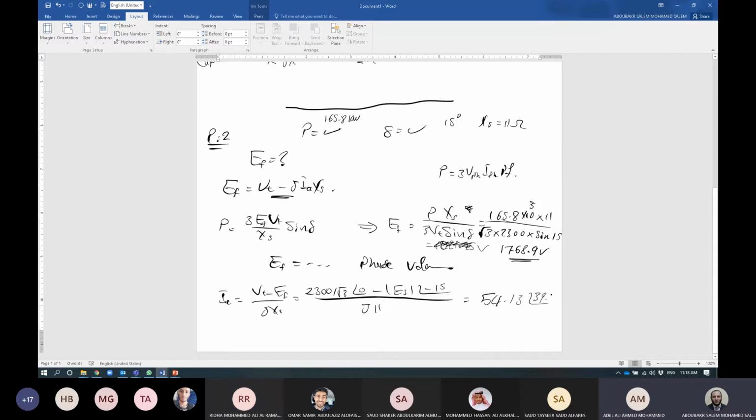So this means the power factor here is lagging or leading? Leading. Exactly. So the power factor equals cosine of this angle 39.7. It's equal to 0.77 approximately, leading.